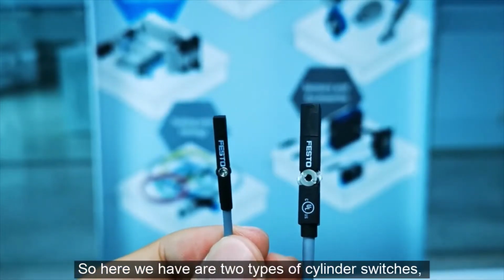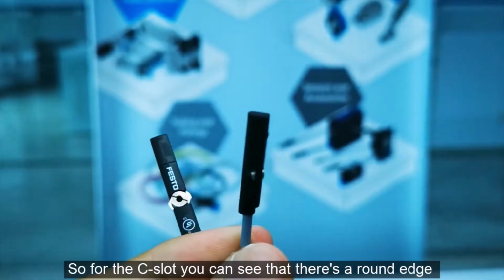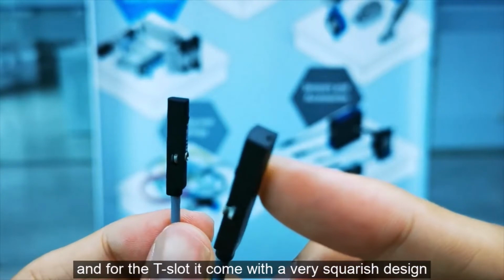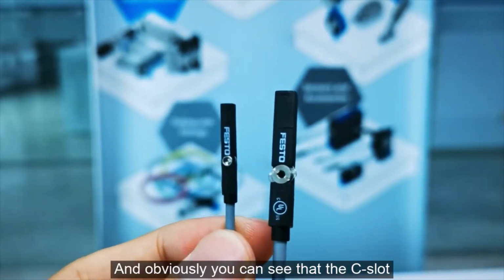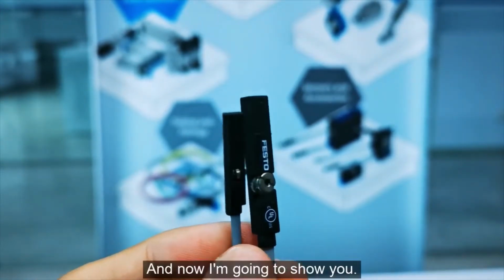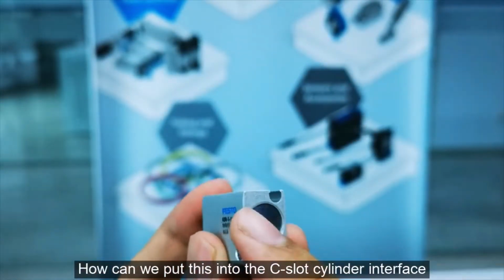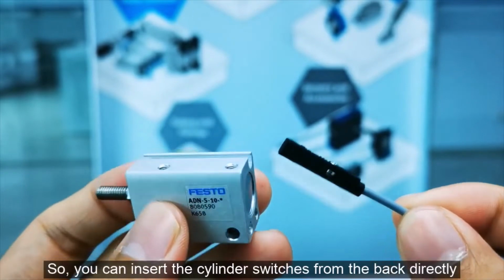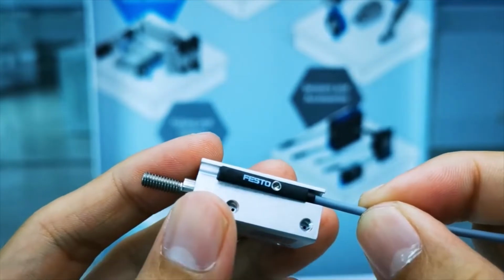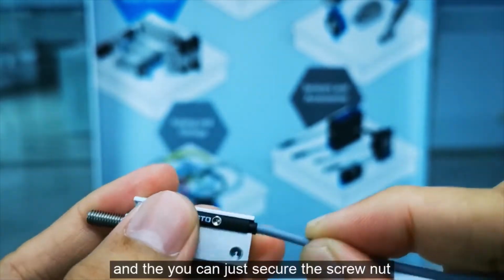So here we have two types of cylinder switches, the C slot and the T slot. For the C slot, you can see there's a round edge, and the T slot is a very squarish design. Very obviously, the C slot is much smaller compared with the T slot. Now I'm going to show you how we put this into the C slot cylinder interface. We can insert the C slot cylinder switch from the back directly, or from the top right away. Then you can just secure the screw nut.